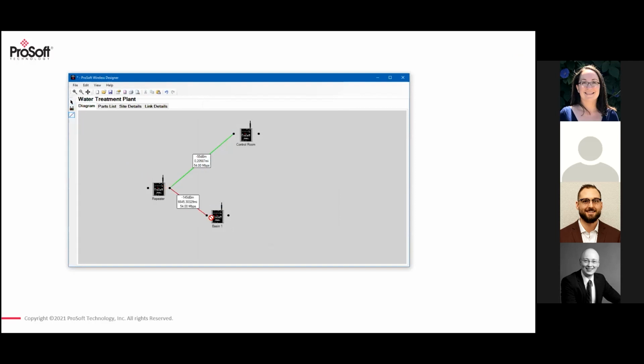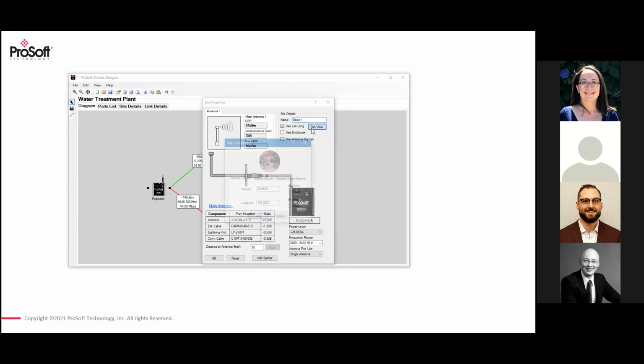Inside plants, we do a lot of business in the automotive industry, for example. So our field application engineers spend a lot of time in those plants before the deployment of the mobile automation, and during and after, to do these site surveys and make sure these antennas have line of sight. That is a requirement. The antennas must have line of sight, and they can help engineer the system in a way that makes sense for that application to ensure that we've got the connectivity required.